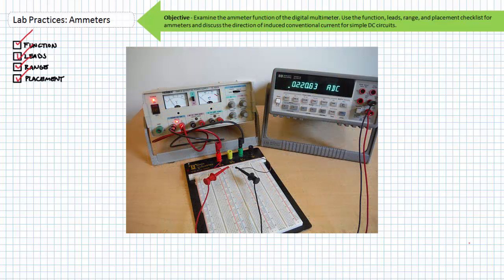Bam, you guessed it, because the parallel combination of a 390 ohm resistor and a low resistance is extremely low. The supply indicates it's an overload and pegging the limit. The ammeter has the least resistance in a parallel combination and carries most of this current. Don't do this. This is dangerous.